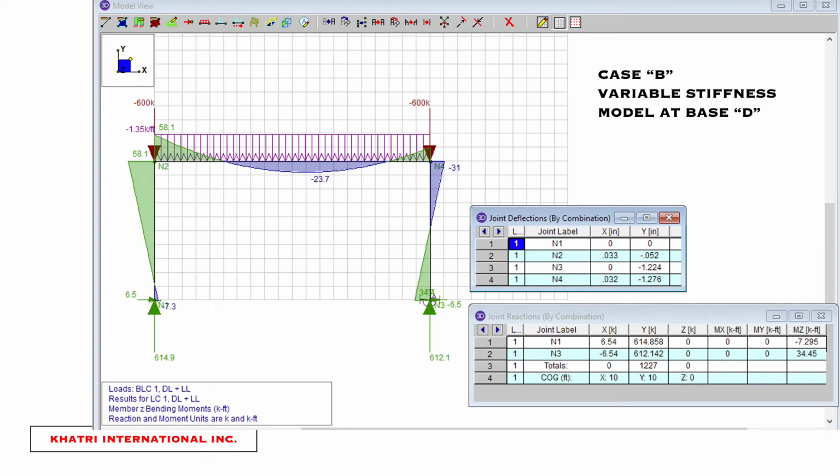This is the same case, case B. Here we have the same deflections. I've printed for you another slide down at the bottom which shows the moment distribution, the moment redistribution, I should say. And again, you're getting asymmetry. You can see the moment diagram on the far left column has shifted dramatically, and the loads have gone up, which puts extra strain on that beam column connection, and also it affects the shear diagram as well.